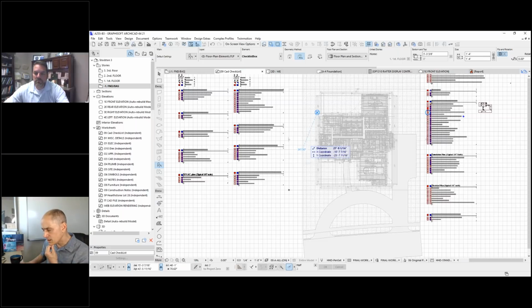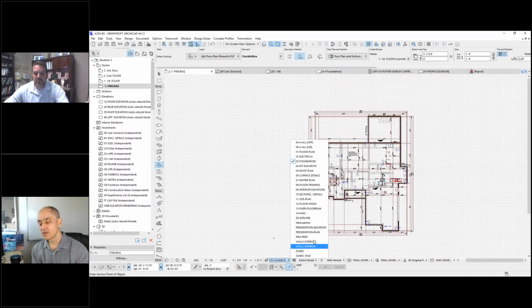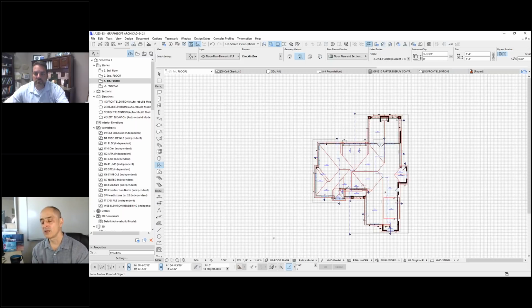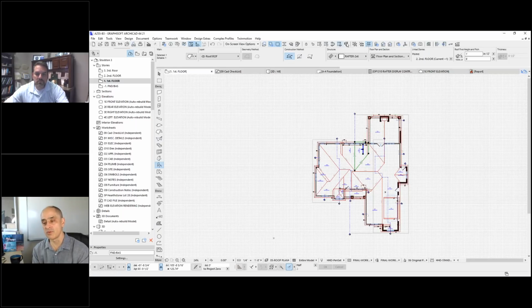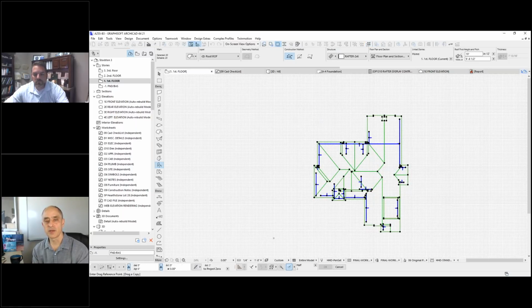So let's see. Todd Hotchkiss asks, the roof wizard thing, please explain. So without going back to doing it, let me just give the 1-minute explanation for those people who looked at it and went, whoa, I didn't know what he was doing. Basically, there is a built-in set of tools for creating roof framing, overall called the roof wizard. You basically draw one or more roofs, your whole roof system, select the roof elements, and then you go to the, I believe it's under the design menu.